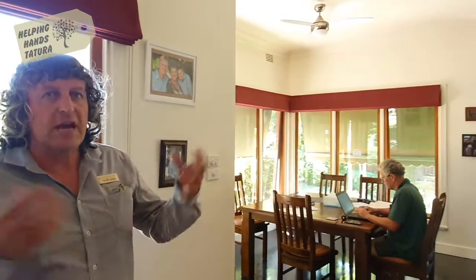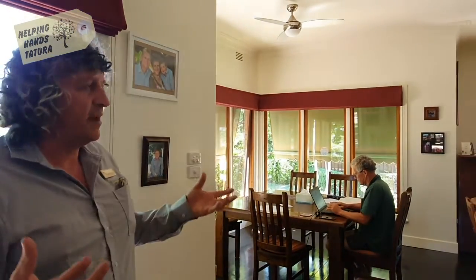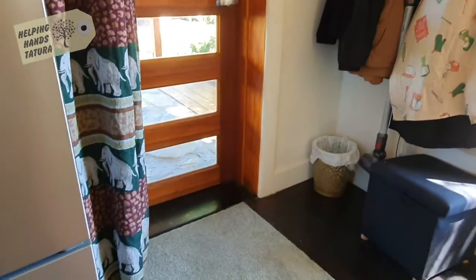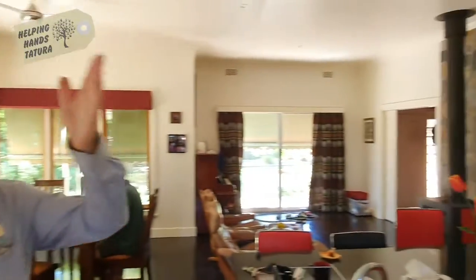Improving the thermal performance of a house is to reduce the amount of air leakage, unwanted air escaping or unwanted air entering the house. So I'm in the kitchen and I look around at what are the opportunities for air to escape from this part of the house. So we've identified the gap under the door. Now I cast my eye around and I see these wall vents.